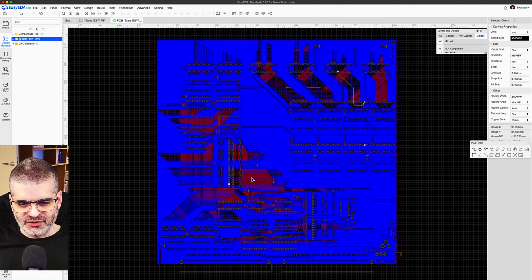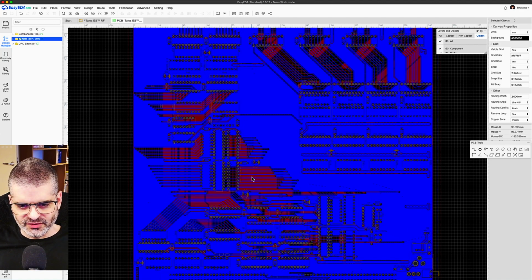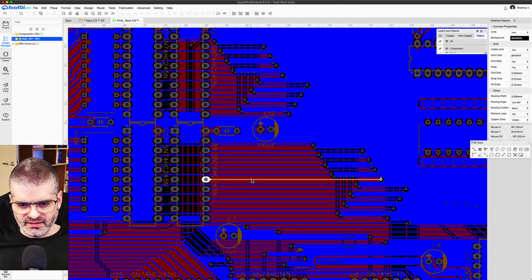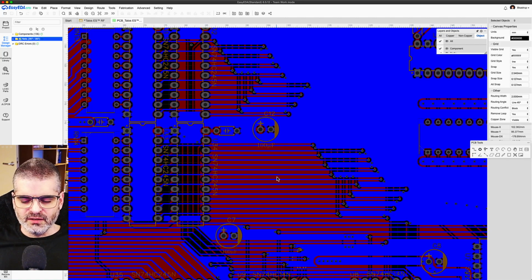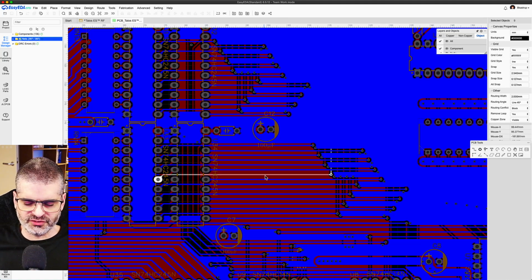And what will happen is that two neighboring signal lines, like this and this, if there were a floating copper fill here at the ground level in between, without the actual ground plane, the copper fill would float, and these two lines would couple to one another via the metal, because the metal is effectively floating at the speed of light, at the wavelengths of the higher harmonics in the circuit.